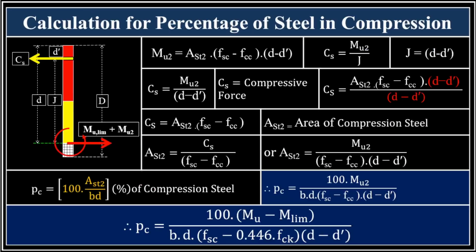Title of this slide is, Calculation for Percentage of Steel in Compression. Alright, let's now move on to a crucial calculation in doubly reinforced beam design, determining the percentage of steel in compression. This slide outlines the formulas and steps involved in this process.